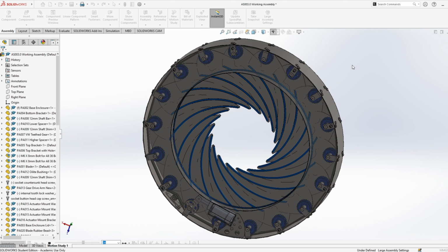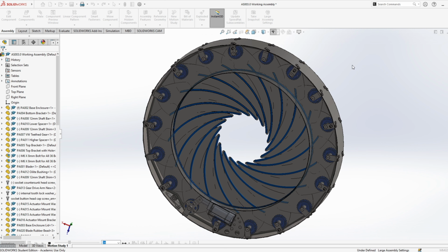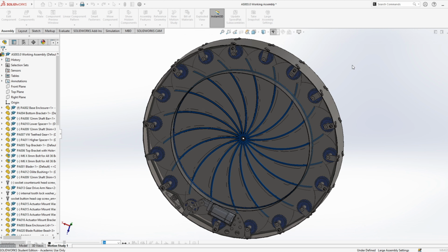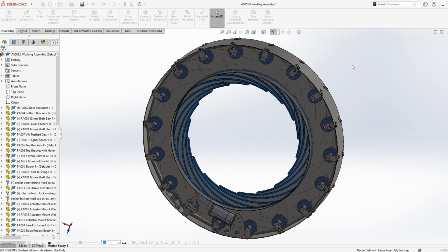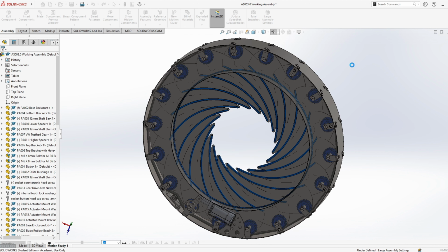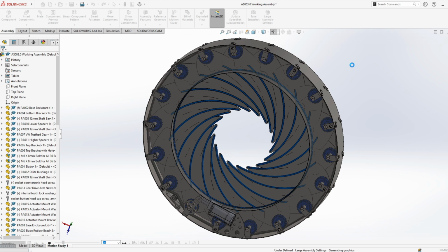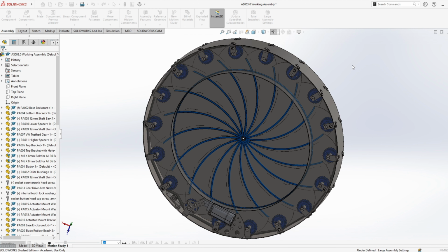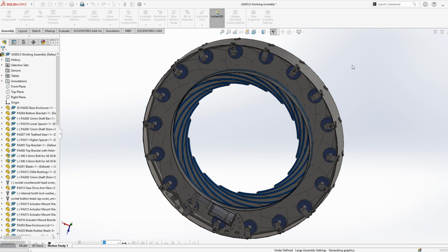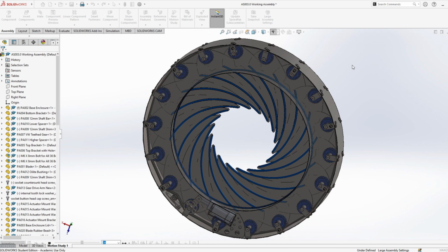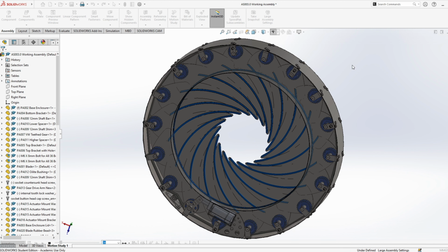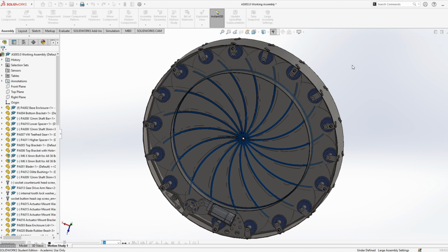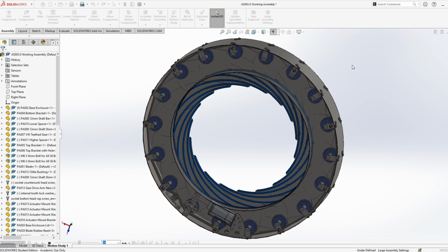So if I increase the number of blades, I'm increasing the number of gears or pulleys. If I increase the number of gears, pulleys, I'm increasing the number of shafts. If I'm increasing the number of shafts, I'm increasing the number of spacers, brackets, bolts, everything. So it's very much the same as your standard aperture. So throughout my design, I have kept creativity in mind, as the entire diaphragm and its mechanical mechanism are on display and are not hidden by obstructing components, such as a large control ring.